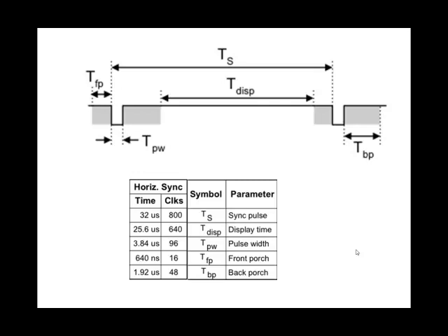Now, it's important to remember that when we're talking about clocks here, we're talking about pixel clocks, which is the 40 nanosecond pixel clock, and not necessarily the 20 nanosecond clock that we're using on our FPGA board.